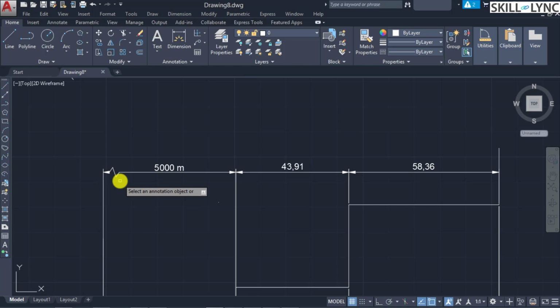Alternatively, we can also remove a jog line. You can invoke the jog dimension line, and on the dynamic option you can see there's a remove option here. Once you click on a previously jogged line, you can remove this jog. So this is adding or deleting the jog line. And suppose we want to modify the location of the jog, you can select this and then use the grips to modify the location. So this is optimizing the jog location.